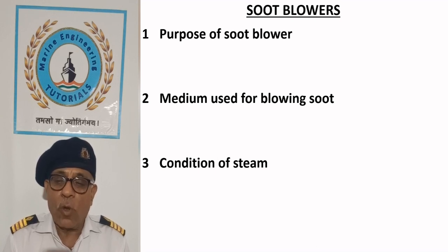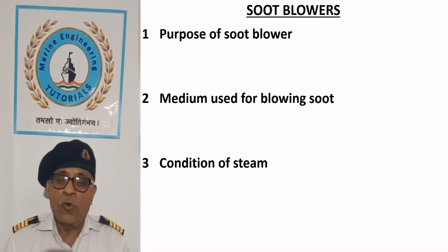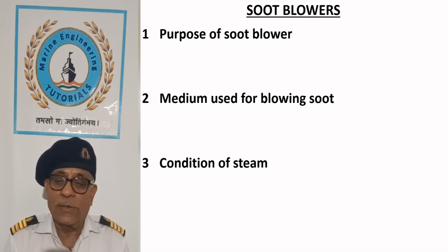Steam pressure on motor ships is low and at the same time it is not superheated, which can affect the bare tubes of the exhaust gas economizer. Present-day forced circulation exhaust gas boilers have gills shrunk onto the tubes, thus protecting them from erosion and corrosion.